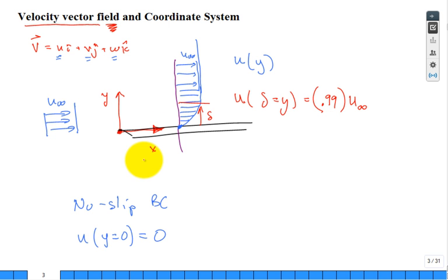If you come over here at this x, closer to the leading edge, well, this is always a challenge. It's still u infinity far away, and yet it's u infinity a lot closer before it does the transition. So this one's, again, a little tricky, but I will say that the velocity gradient is larger near the leading edge, meaning the change in u with respect to y evaluated at the surface, y is equal to 0.